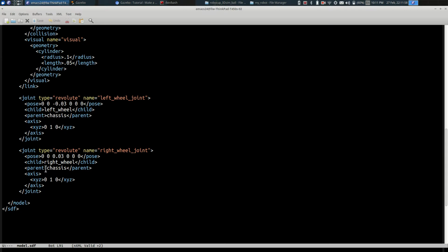And if you play your cards right, rather than doing a URDF, you'll make a Xacro file, and you'll add to that Xacro file those things that are not needed by things like RViz, but RViz will ignore the extra things like inertia, friction, things like that. RViz will just not pay attention to it. And so you can use one file for both Gazebo and for RViz. And believe me, if you have a robot with more than 2 links and you try to maintain separate SDFs and URDFs, it will drive you crazy because you'll never get them to match up. So best practice is to have just one file.